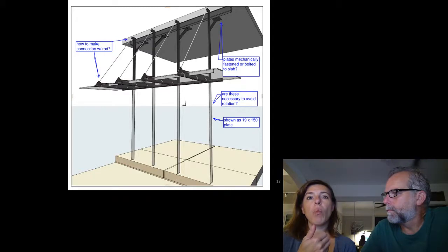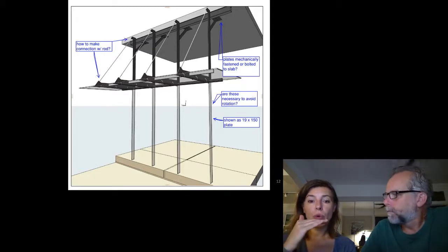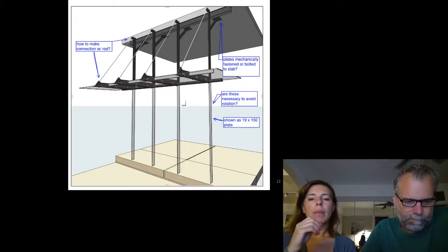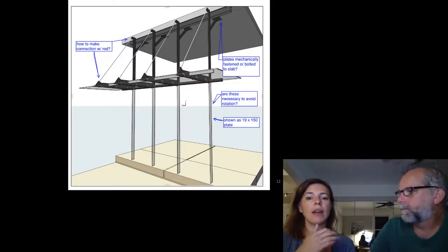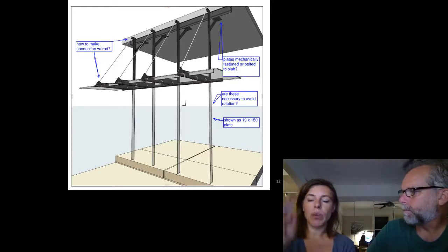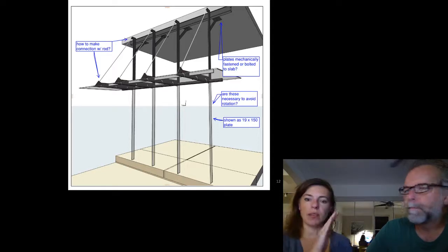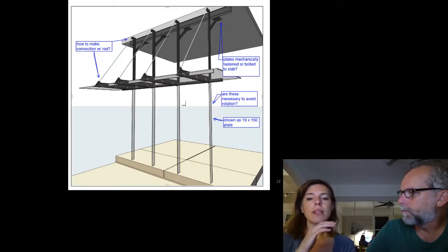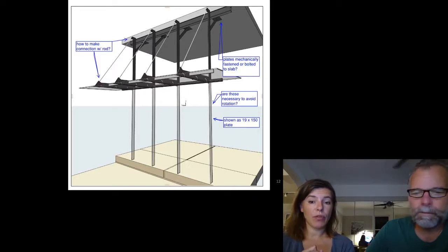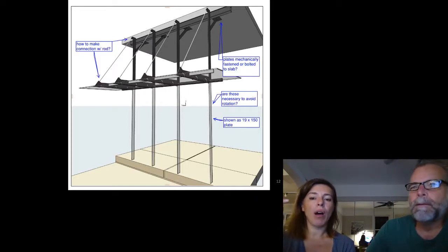And once I needed to moment connect for those loads, the member needed to be the size it needed to be, and the architect said, we just want that visually, we don't want to change our member sizes around the building. So I took that and reapplied it through the entire system, and once I had solved that, even in the spots that didn't have as high of an uplift force, now without the rod,